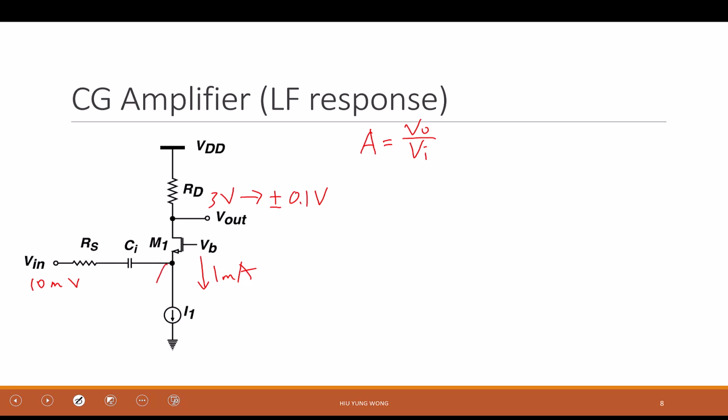If I call this point X, you already know Vout over Vx because you did the small signal derivation before, KCL and KVL, right? So you say, okay, I'm going to do it in 2 steps. But giving me Vout over Vx is useless because I also want to know Vout over Vin, right? So you also need to know Vx over Vin, good, right? Just a chain rule, right?